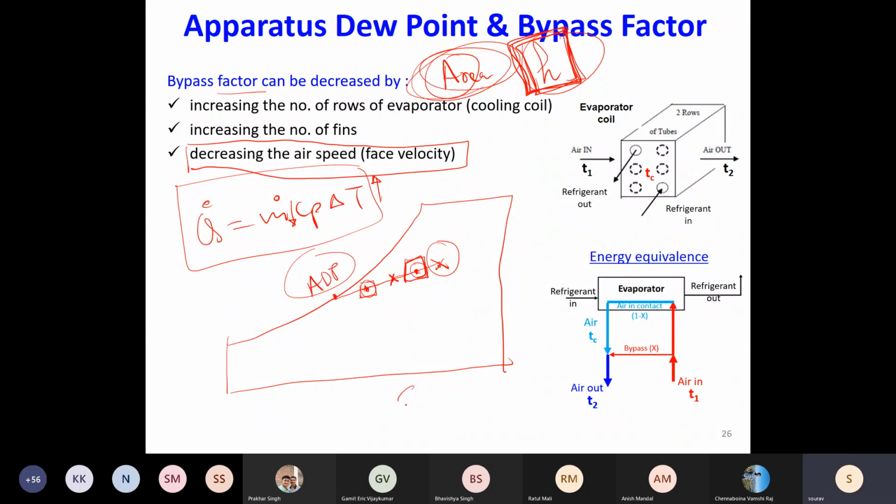So please understand that effectiveness is just defined on the basis of the temperature differences. So maximum potential in the denominator and actual whatever happens. Okay, so then in that case, if you move to smaller and smaller speeds, you will have much larger temperature drop across the heat exchanger.